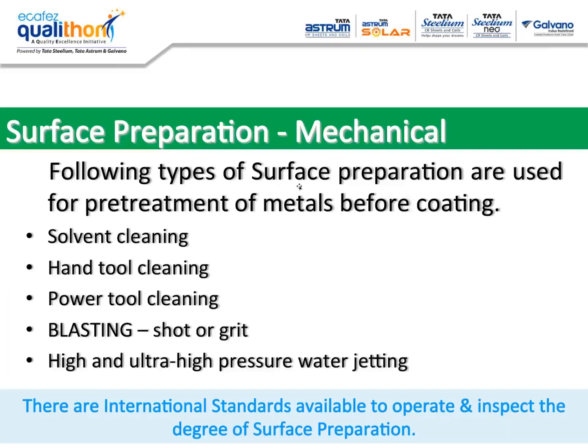Surface preparation, mechanical methods. The following types of surface preparations are used for pre-treatment of metals before coating: solvent cleaning, hand tool cleaning, power tool cleaning, blasting or shot or grit blasting, high and ultra high pressure water jetting.